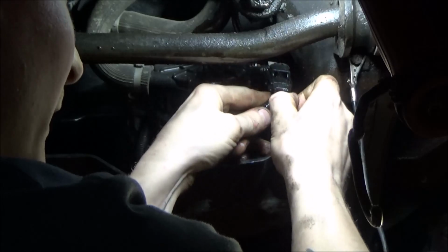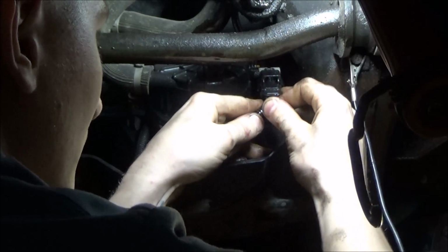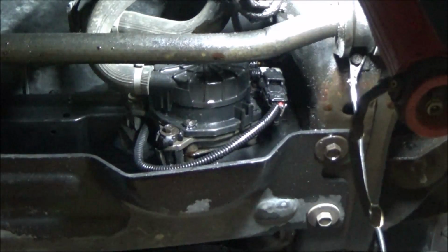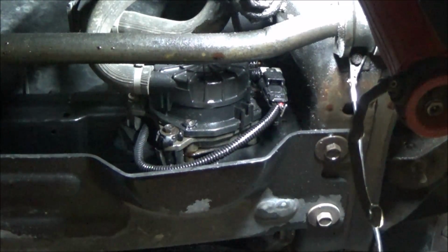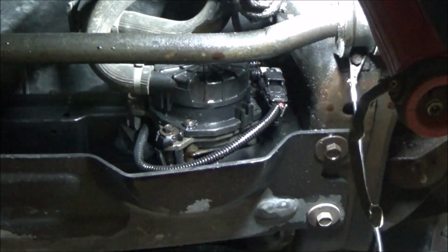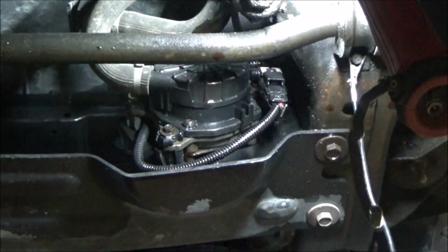So I'm just taking this T-pin going into that black wire. And this being a much higher amperage load, guys, I'm actually going to back probe it, and I'm going to use my test light to check this ground. The reason we did not do it with the solenoid is that this test light is so hot, it draws almost an amp of current flow. We would have just energized it if it were good. But this being a 30 amp motor, I'm definitely not worried about energizing it accidentally with this test light.